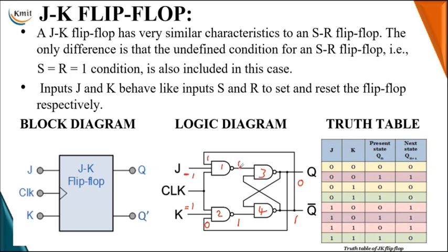Hence the first NAND gate output will give 0. Upon the third NAND gate input being 0, the output state now changes from 0 to 1. That 1 is applied as an input of the fourth NAND gate. Hence the complemented state is transferred from 1 to 0.